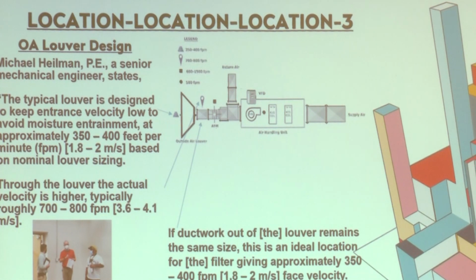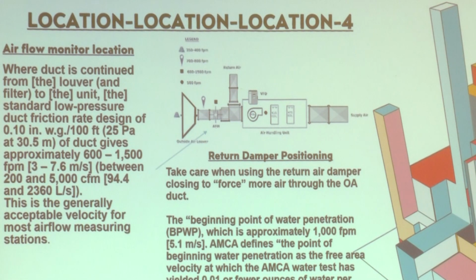So it's important that we maintain this louver design per this specification to make sure that everything is done right and that the systems coming into the outdoor air work properly. I have a job right now where the outside air louver system is designed so badly that the velocity of the incoming outdoor air is so fast that it affects the actual operation of the cooling coil.